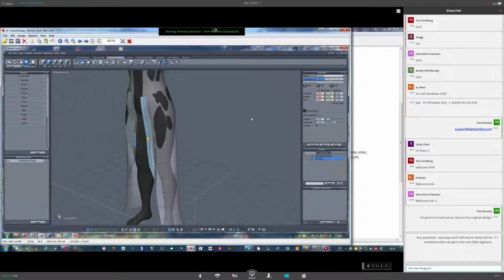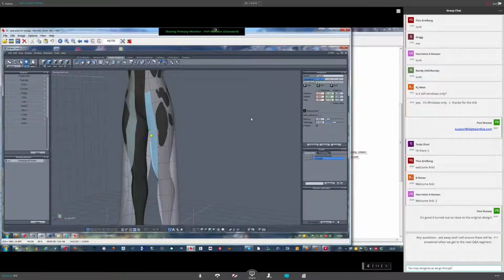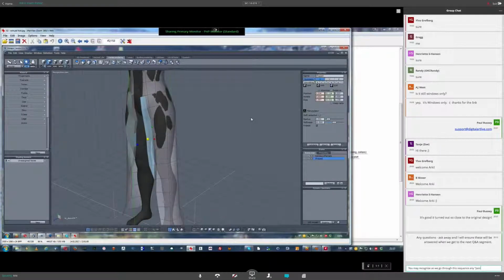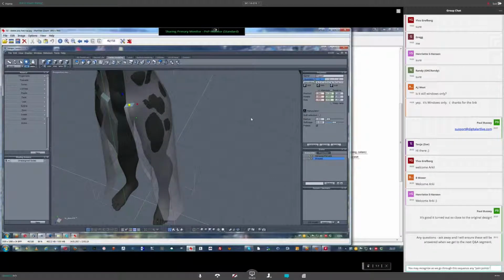This is also part of the process. So this might be interesting for a few of you, how to create folds which look more or less believable or realistic. This is also extruding. You select a polygon row or an area of polygons and extrude them outwards. Then you delete the top polygons of these box shapes and weld the remaining polygons back together.